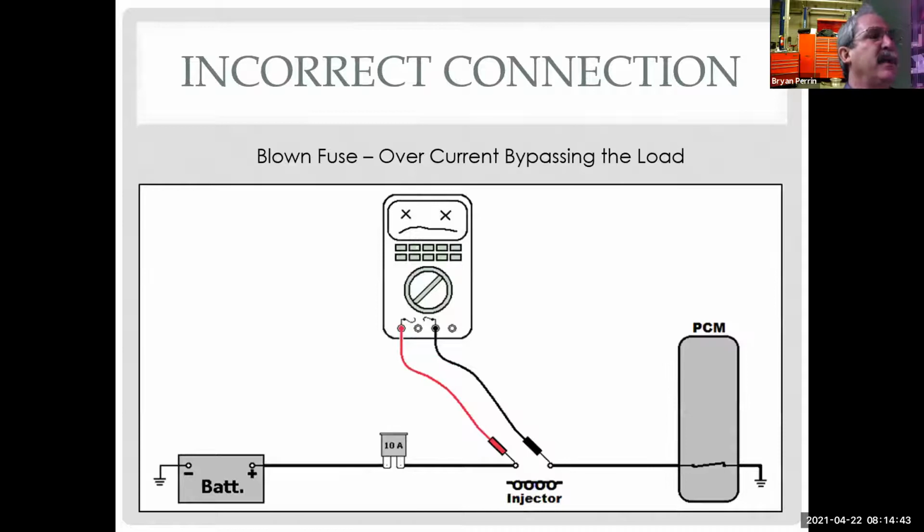Here is a mistake that a lot of people make. They take the load out of the circuit and then put the meter in place of the load. And what happens? I have a very sad meter because now there's no load. All I have is power supply and conductors. So I've got the power supply, comes through here, up, used to go through here, come down through here, all the way over to here. There's no load in the circuit. If there's no load and we apply power, what's going to happen? We start melting things. And that's why my meter is sad. It's having a bad day.